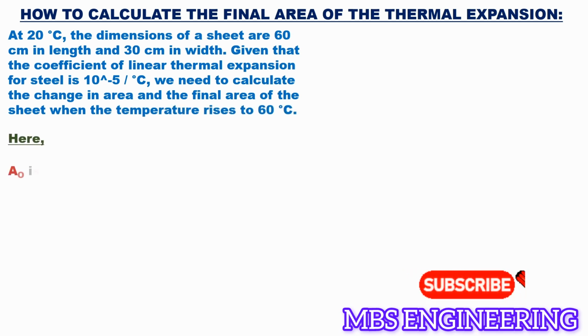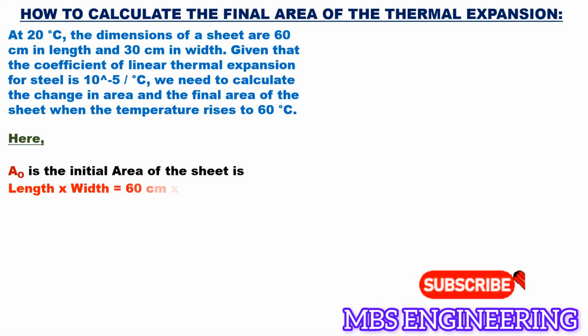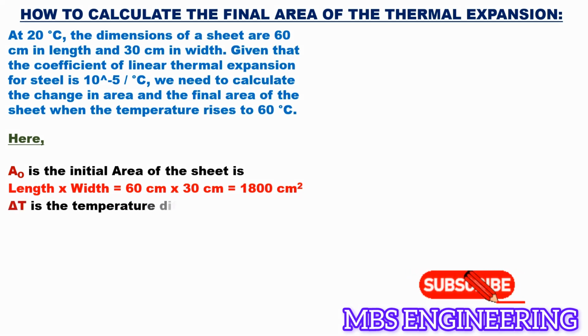Here, A0 is the initial area of the sheet. It means length into width, so 60 centimeters into 30 centimeters. Therefore, the initial area A0 is 1800 centimeters square. Next, delta T is the temperature difference. The final temperature is 60 degrees Celsius minus the initial temperature of 20 degrees Celsius. Therefore, delta T, the temperature difference, is 40 degrees Celsius.